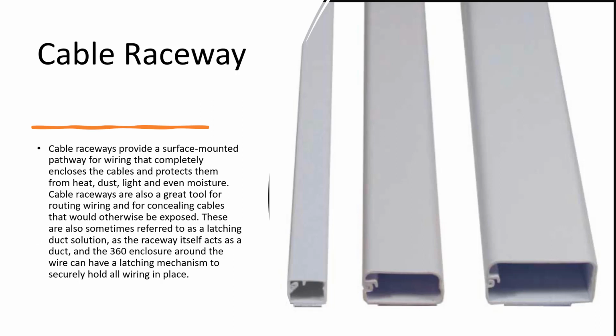When viewing the types of raceways included in the definition, they can be broadly divided into circular raceways, which is the conduit I discussed earlier, and non-circular raceways, such as wireways. We have two specific types of circular raceway, which are conduit and tubing. The cable raceway that we discuss in this slide is the tubing.